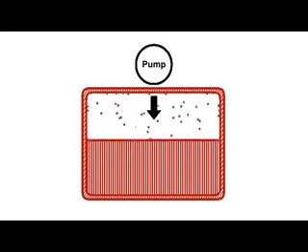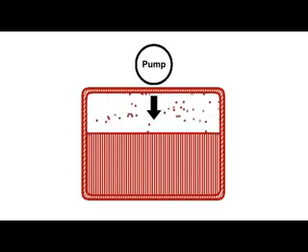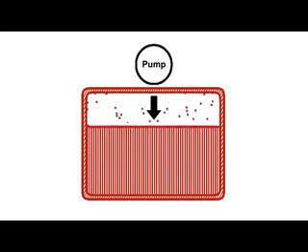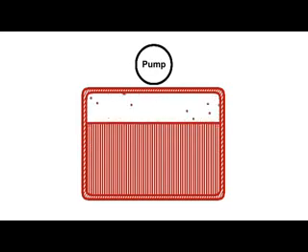This is important stuff because it means that if we put coolant in a loop, boiling can be induced by reducing the coolant's pressure in the evaporator, and this makes the evaporator cold. And condensation can be induced by simply increasing the coolant's pressure in the condenser, making it warm. And so it goes, round and round, low pressure to high pressure and back, evaporation to condensation and back.